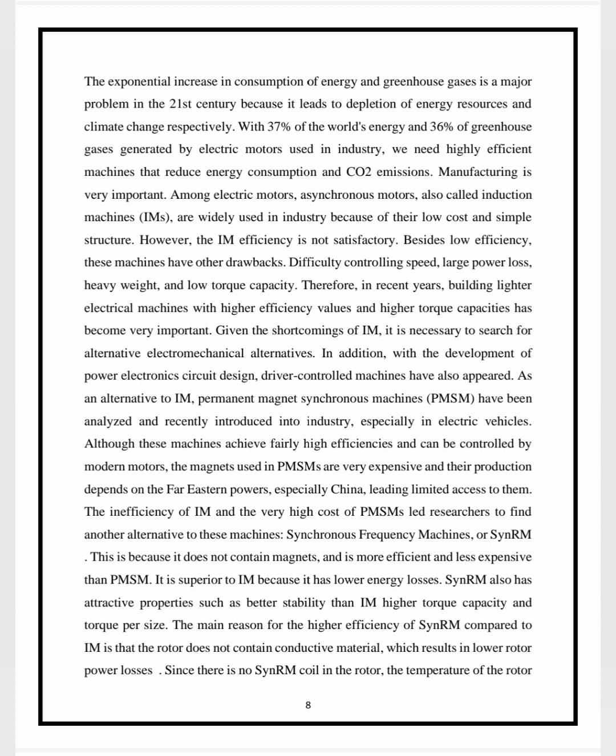Among electric motors, asynchronous motors, called induction motors, were widely used in industry because of their low cost and simple structure. However, induction motor efficiency is not satisfactory. It is not up to the mark. Besides low efficiency, these machines have other drawbacks, for example difficulty in controlling speed, large power losses, heavy weight, and low torque capacity. Therefore, in recent years, building lighter electrical machines with high efficiency and high torque capacity is the basic demand, so these are very important for today.